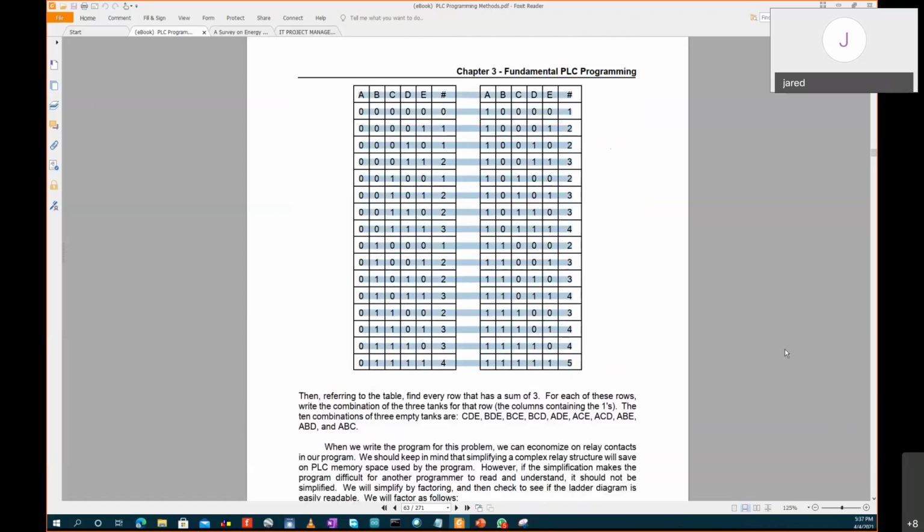And if you don't do well, you might mix up the logics, and those relays, normally open, normally closed, will clash. These are all possible combinations. How many do you have? 32 combinations. If you don't do them carefully, if you don't minimize or simplify the combinations, you may end up having a bug.